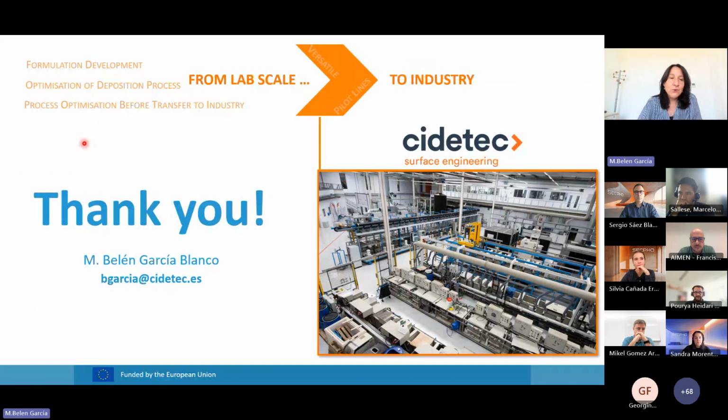So the main message that I want to tell you today is that the e-coating process can be optimized by modifying the formulation or also by optimizing process parameters to have coatings with high corrosion and chemical resistance. And that this process can be applied by immersion to treat the whole areas of a part and also selectively by using the brush plating technology. So thank you all for your attention.